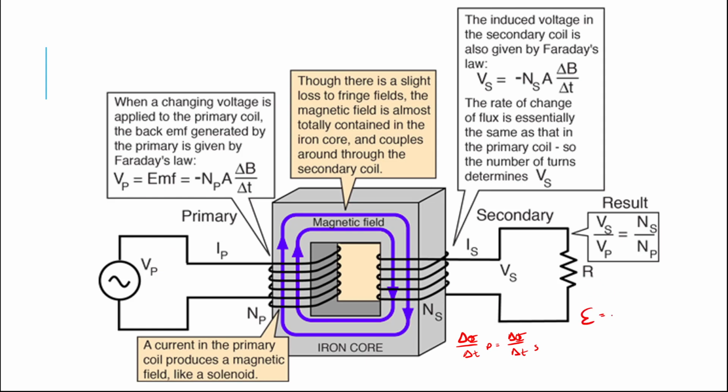So we think about Faraday's law. Faraday's law says the EMF is equal to the rate of change of flux linkage: the rate of change of flux multiplied by the number of coils. The secondary coil has the same rate of change of flux, right? So that whole rate of change fraction is the same on both sides. So this comes from my first coil. But if I change the number of loops, then I must also change the EMF over here. That's really the only place that this comes from, okay? This essentially equals this, and I end up with a ratio. So I'm changing the number of loops so that the EMF changes, because both of these coils experience the same rate of change of flux.